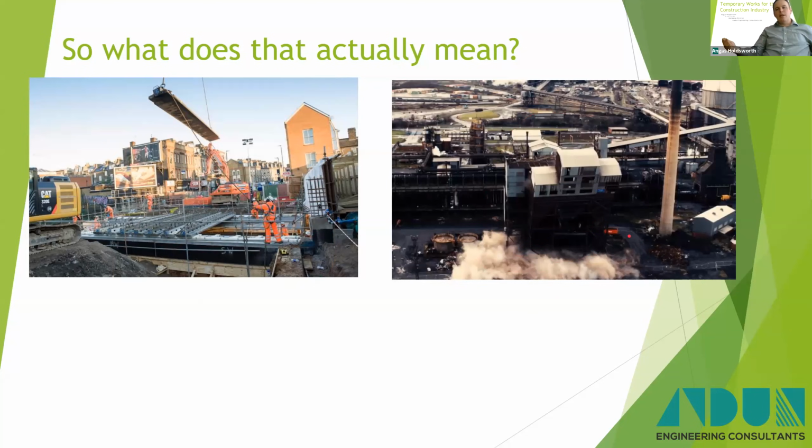When you're pre-weakening a structure, it has to stand in the temporary condition, i.e. you have to look at the wind forecast and make sure that it's acceptable before you do the final cuts. But the structure could be standing for a couple of days in the partially pre-weakened condition until the final cuts are made on the day of the final blowdown. So all these things have to be considered as temporary works.